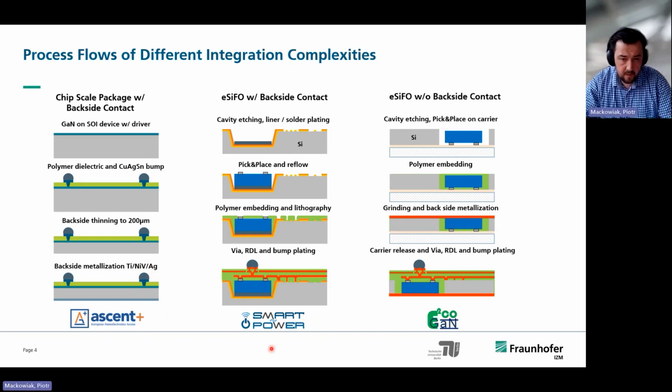In another approach, where we had an embedded silicon fan-out approach with a backside contact, we etched a cavity into a silicon wafer and applied a liner metallization and placed the solder into the cavity. We then picked and placed and reflowed the active chip into this cavity.